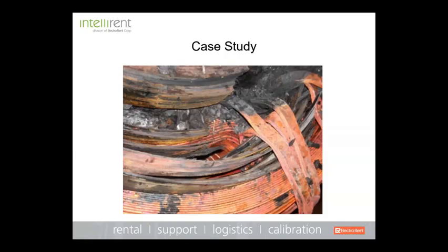It doesn't take that much longer to run, and most of your power factor test sets have that capability, either inclusive in the test set, as an accessory to the test set, or as part of your winding resistance test set, like a Raytech. So I would strongly suggest that you include leakage reactance if you have no clue as to whether or not you've had through faults.